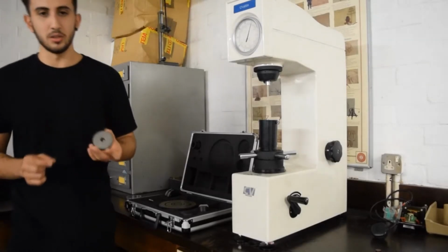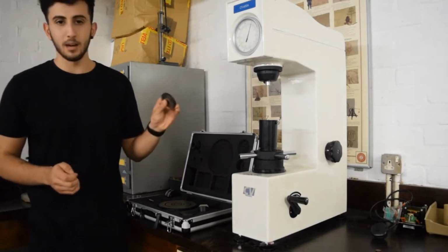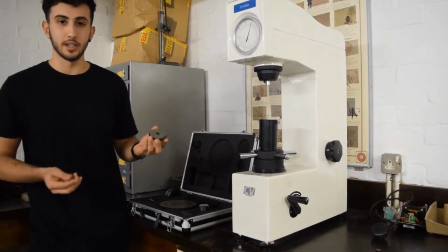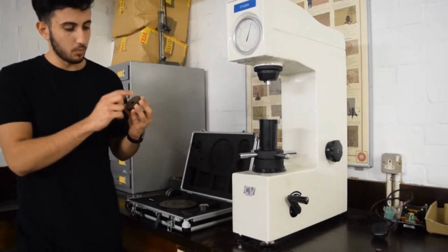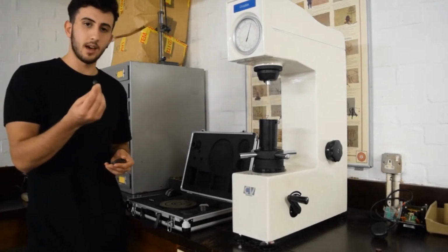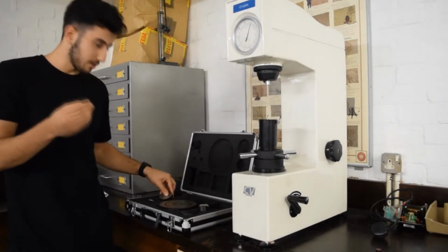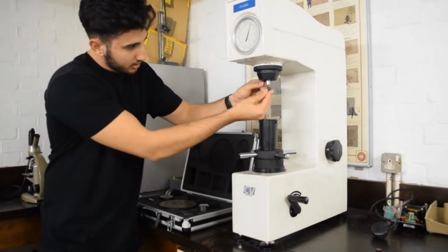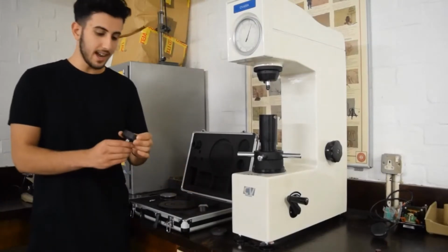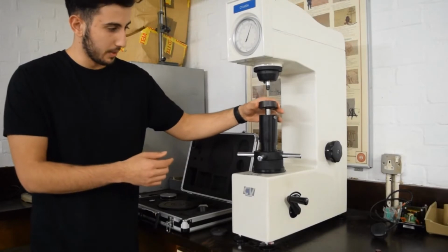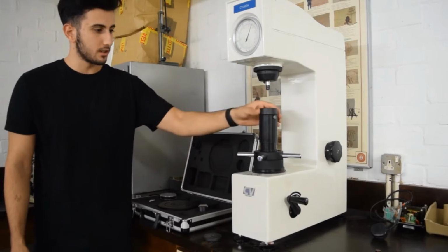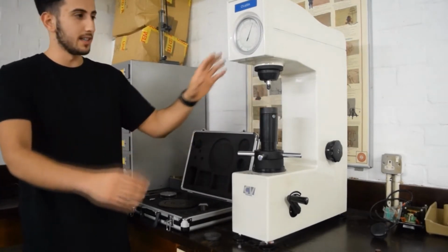Material like mild steel is used as a calibration test piece to check that the machine's in working order and is up to calibration. It's got numbers written on here that specify its actual hardness. This is mild steel, so we'll be using a scale B indenter with a steel ball. Firstly, you want to put it into the holding chucks and tighten it with the knob provided. Next we want to put in the workbench that we'll be putting the specimen onto. These can come in various different shapes because you might have a rod that you want to test.